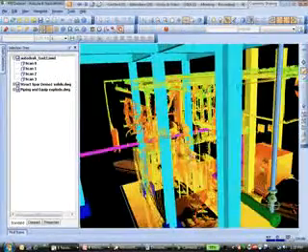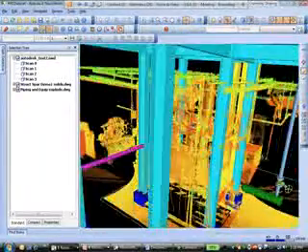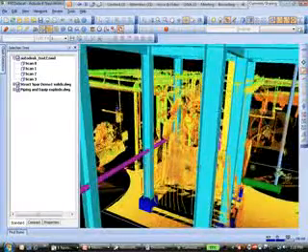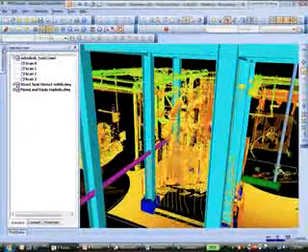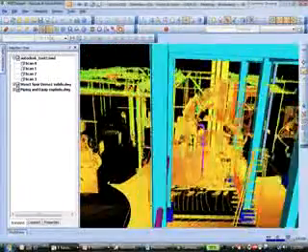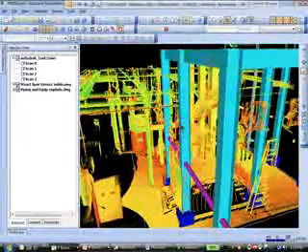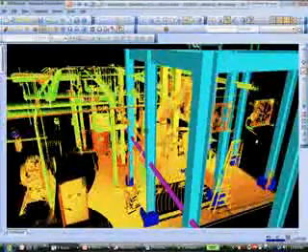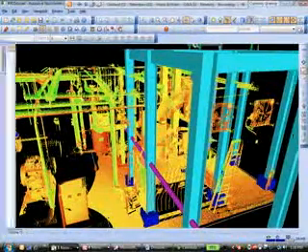So let me go ahead and move in here. And this is really where it becomes useful, where you're working with existing and you have new, or maybe there's some demolition. You want to be able to take into account the space that's going to provide. Once I have this information all lined up and sequenced inside of this building, I can now leverage the clash detection. So if I open up the clash detection in Navisworks,